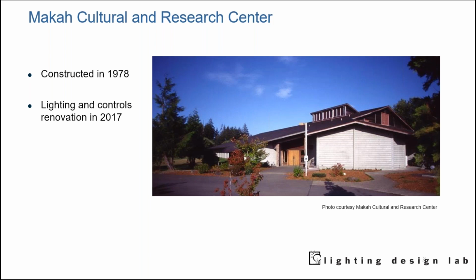Unfortunately, the fan coil units never worked well, and maintenance became a really huge issue. This meant that the artifacts were being subjected to more heat than allowed and required continuous monitoring by the curators and museum staff under the oversight of a conservator who set the maximum illumination at the artifacts to maintain maximum lumen hours on those artifacts.